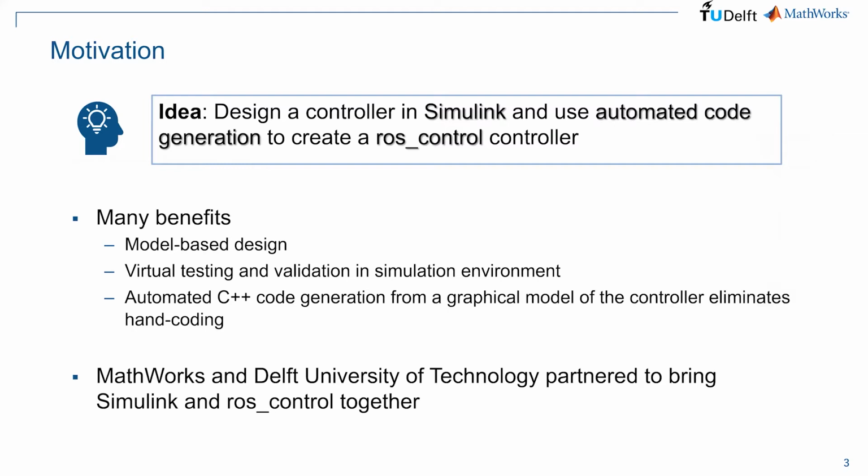So our motivation comes down to why not take that infrastructure from Simulink for design and testing of controllers and try to integrate that a little bit better with what we have in ROS. And in ROS, we have something called ROS control, which actually allows us to run controllers in a hard real-time execution context on the one side, and on the other side with standard ROS interfaces.